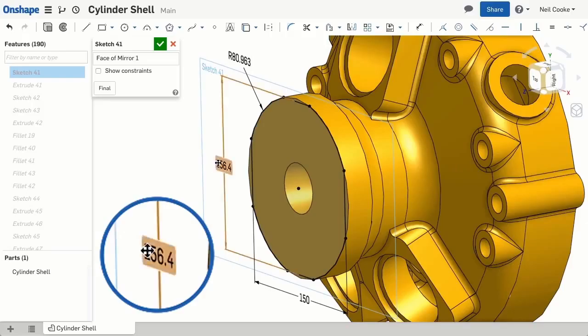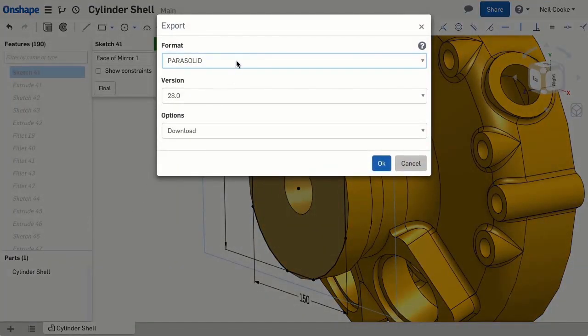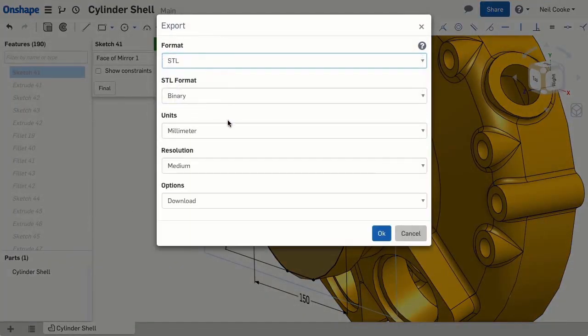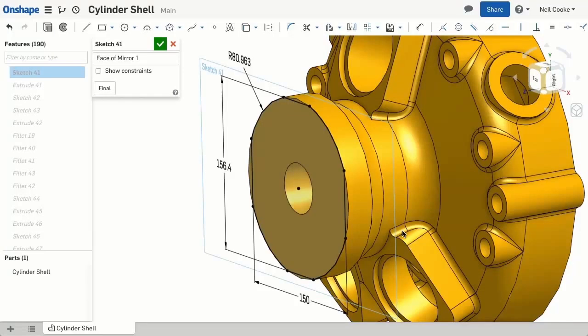Or if you're working on much larger parts, you can mix feet and inches, such as 1 foot plus 6 3/4 inches. Note the positions of the parentheses to make sure the value is calculated correctly. And finally, if you prefer to design in inches, but your 3D printer only works in millimeters, you can override the units when you export the STL file, and the part will be printed at the correct size.